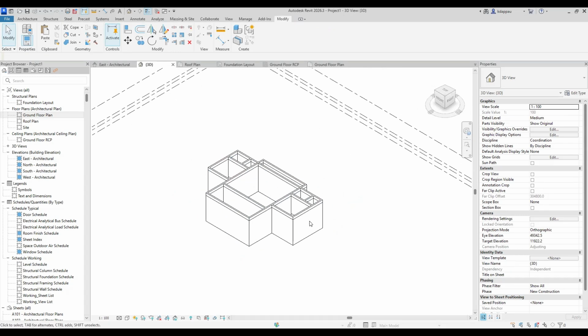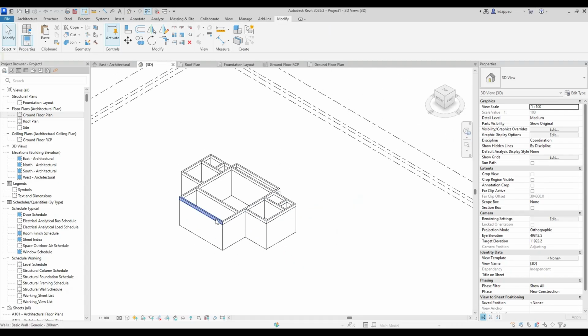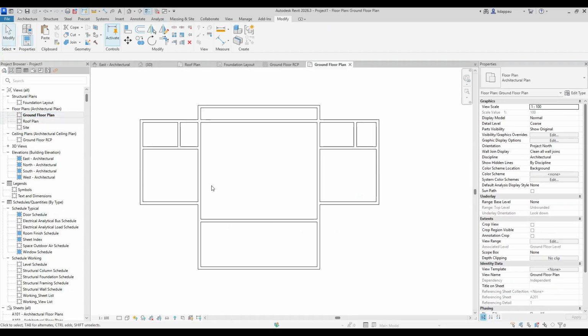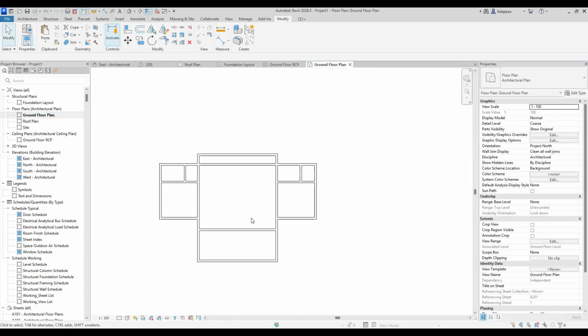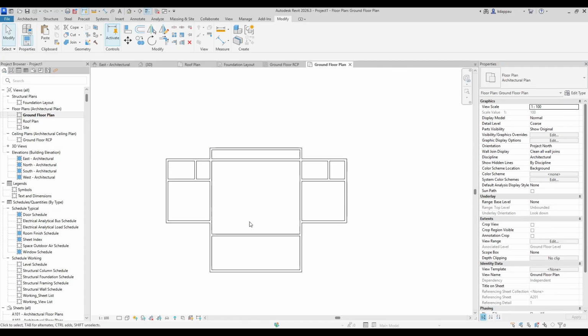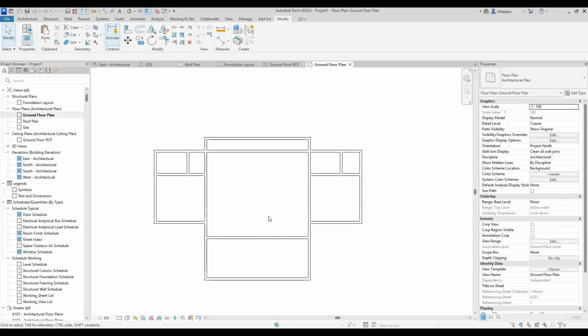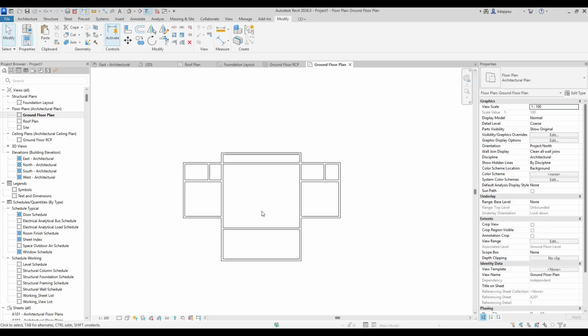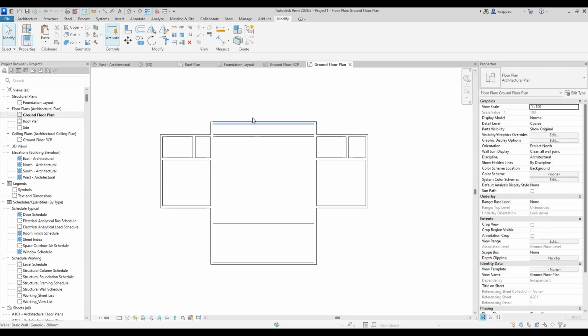Now we've done the walls. The next thing that I can do is that I can begin to add my floors. So I'll go to the ground floor plan, then I can begin adding my floors. Now, when you're adding floors, one thing should concern you. Normally, if you go into a building, not all floors have the same elevations. Maybe at the terrace level here and then the terrace level here, the elevation might be different. This elevation, there might be a drop of 150, so that those floors might be drawn separately. Then internally, if they are the same elevation, then you do them one.